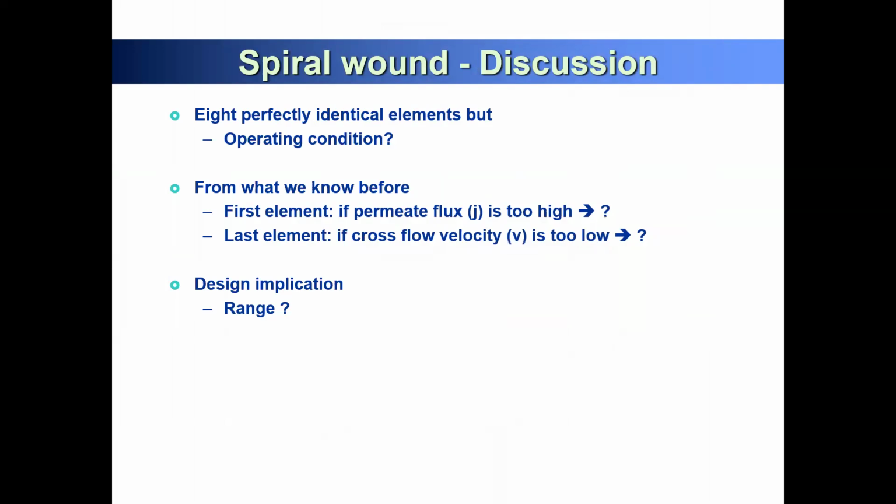When you have water filtration pre-treatment directly, you have a good quality of clean water to the RO. But when you have only a media filter, larger particles will still pass through compared to the ultrafiltration membrane, so you have a higher fouling tendency. So it shows the different treatment will affect your RO, but that is another weakness of our RO membrane software.